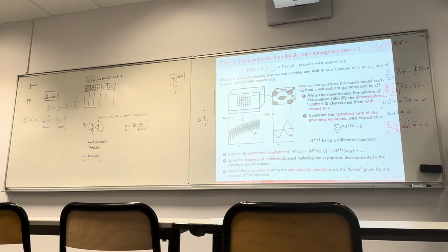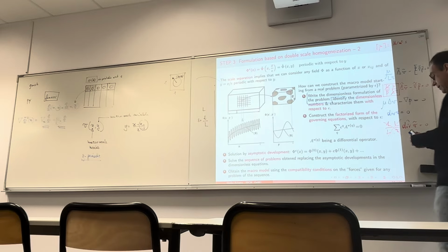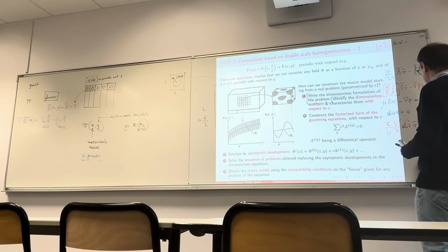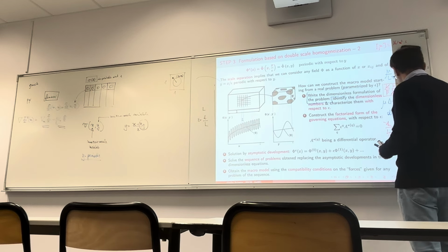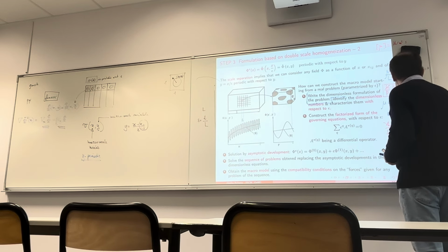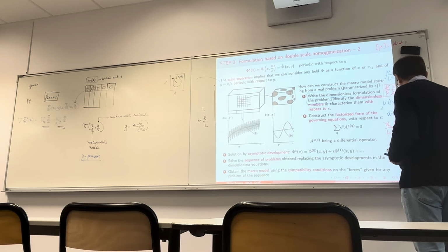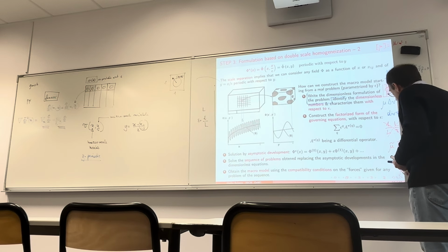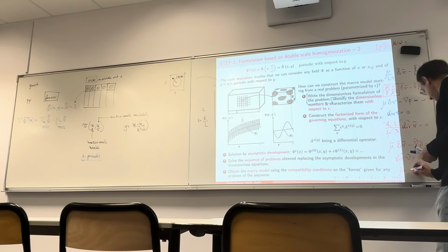In order for this to be 0, divergence tilde of V tilde should be 0. So in the end, your problem reduces to mu tilde Laplacian tilde of V tilde minus gradient tilde of P tilde equals 0, and divergence tilde of V tilde equals 0, where I called mu tilde the dimensionless ratio mu by P bar tau.